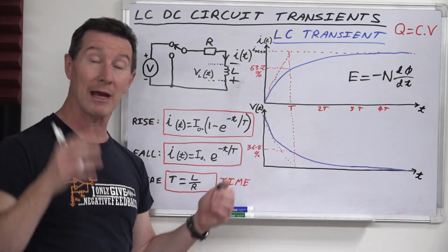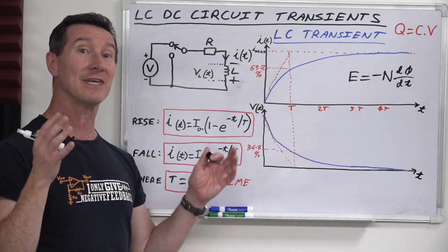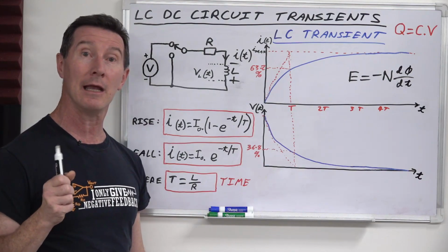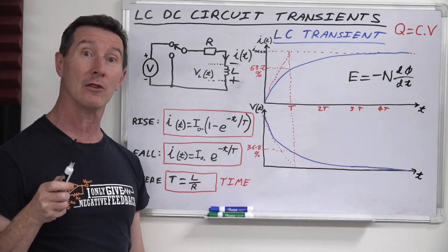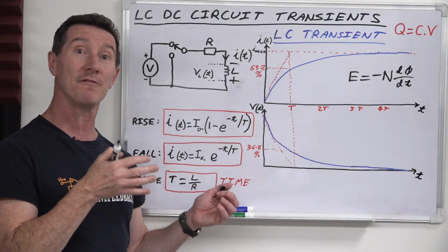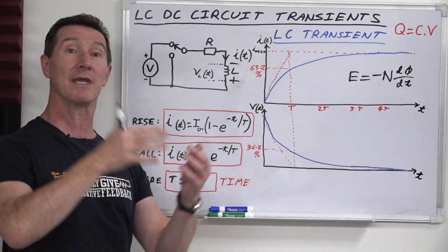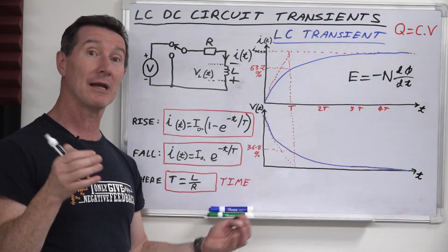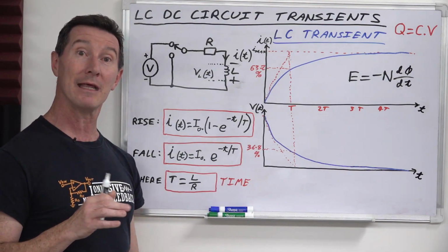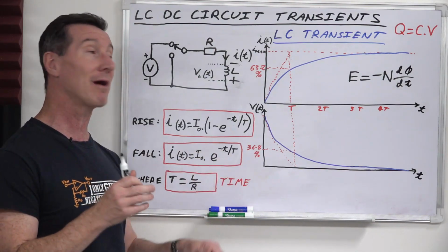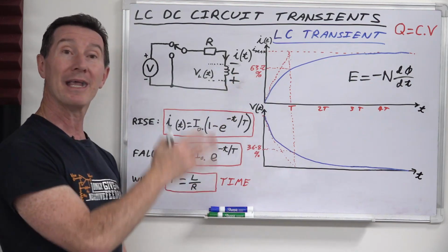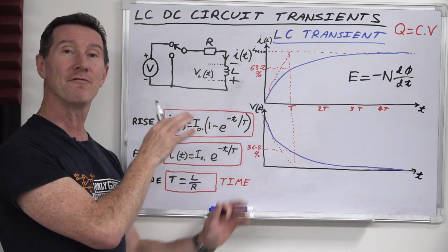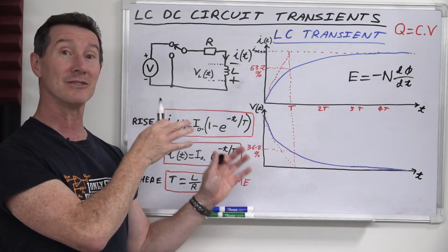And that's how you can generate large spikes and things like that. For example, in the magnetic fluoro ballasts in the old fluorescent lights, the collapsing magnetic field generates a large voltage which then creates the arc and starts up the lamp. That's how the starters work in the magnetic fluoro ballast. You can actually generate large voltages by collapsing a magnetic field, and this is why inductors have some uses that capacitors don't.